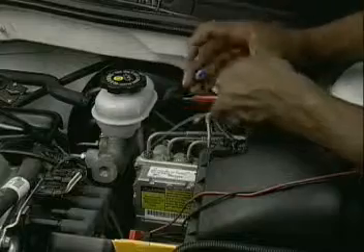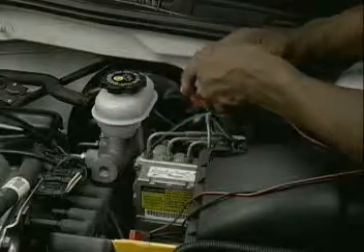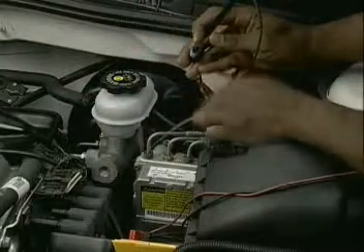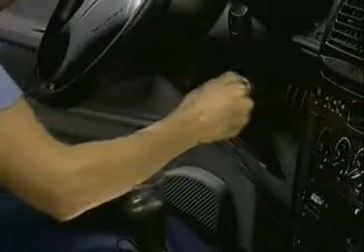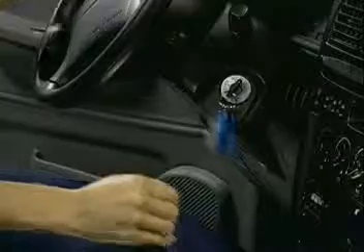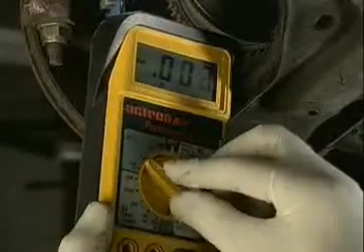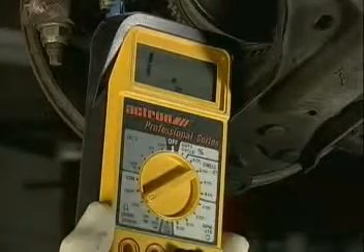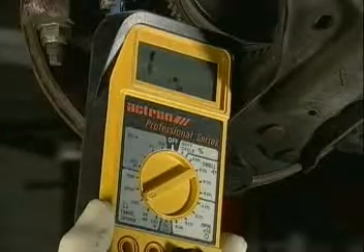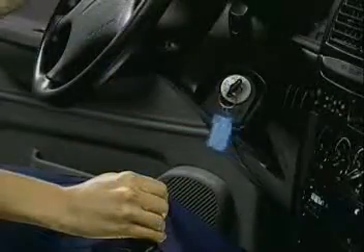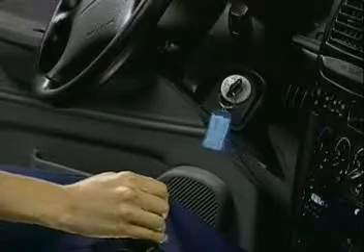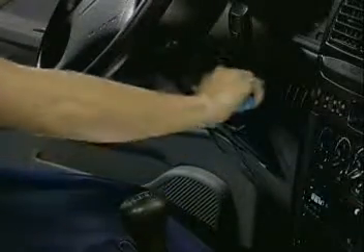High resistance in connectors can be confirmed with a voltage drop test across the connection using a digital multimeter. Voltage drop tests must always be done with current flowing through the circuit. High or low resistance of a sensor can be checked using a digital multimeter using the ohms function. Test for continuity or resistance using a digital ohm meter must always be done with the circuit unpowered.